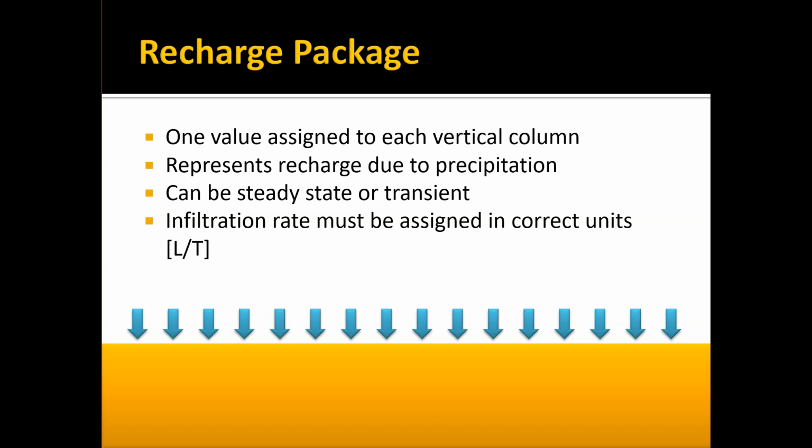And that would be a relatively wet location. And so if your length units are meters, you would take 0.15 meters, and then to get it to meters per day, you would divide by 365. And that's a typical way of coming up with recharge in the proper units, and also estimating a rule of thumb.